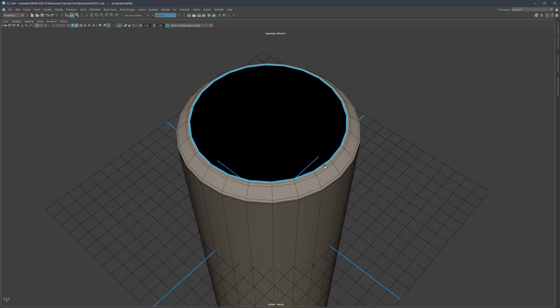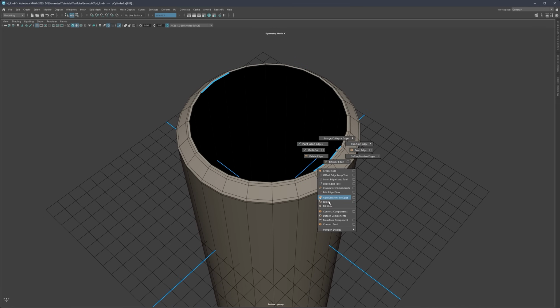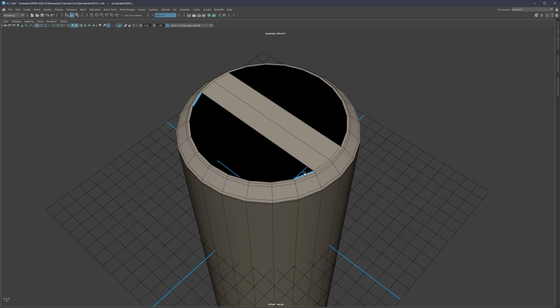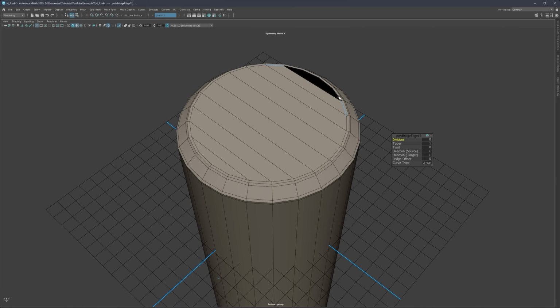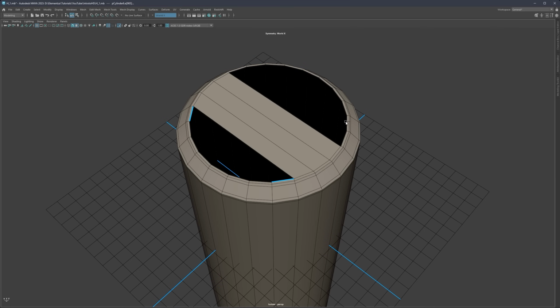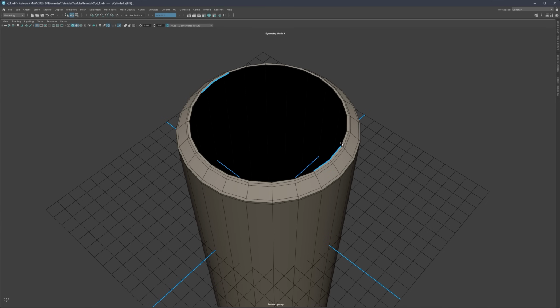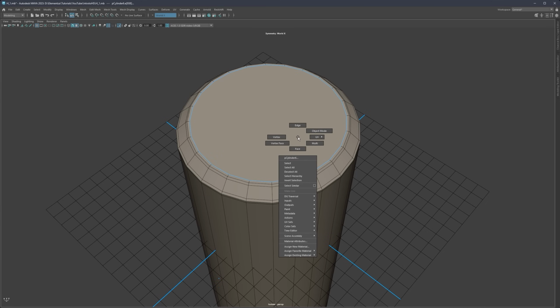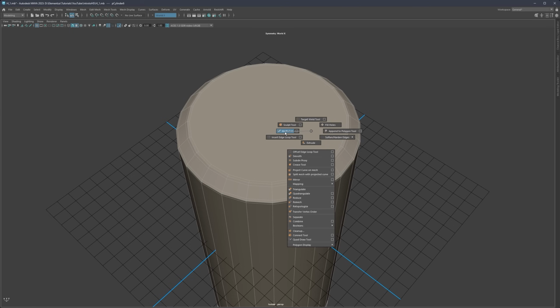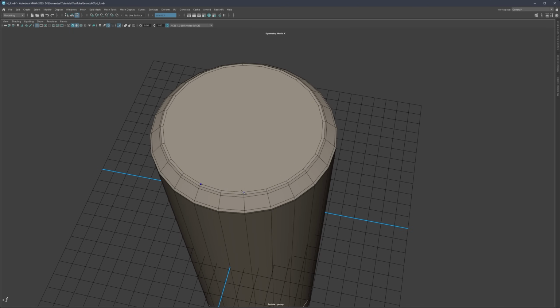It really doesn't matter. If you do, let's say, bridge like this, and then simply continue doing G, you're maybe going slightly faster. So let's select everything, hit G. Or if you decide to do it the other way around, with the Fill Hole option, you would select everything, go to Shift right-click, Fill Hole, and then simply use multicut. So let's say we go to multicut, and now we need to simply connect all the points manually.